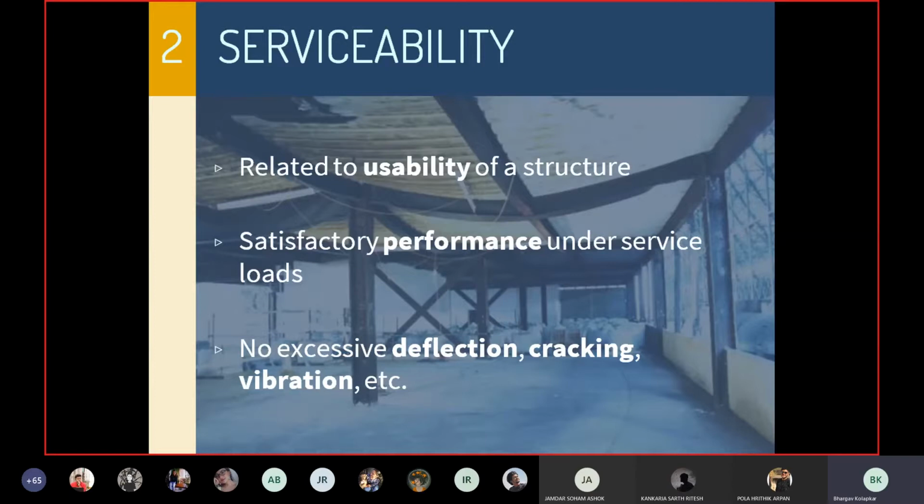It was discovered that the more you try to resist wind, the more force it is going to exert. So a lot of bridges that have been designed after have what we can loosely say is a deck that has openings in between, say a truss deck, which does not provide a lot of resistance to wind. We have looked at this before: whenever there is resistance, there is stress. If you allow wind to pass, it is not going to have resistance. If you do not let it pass, it is going to exert force.